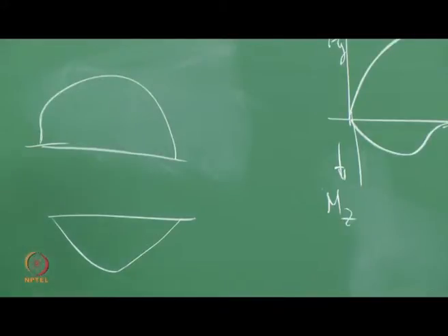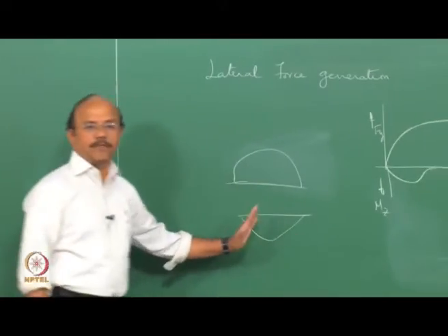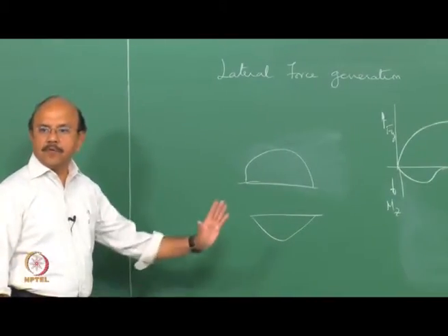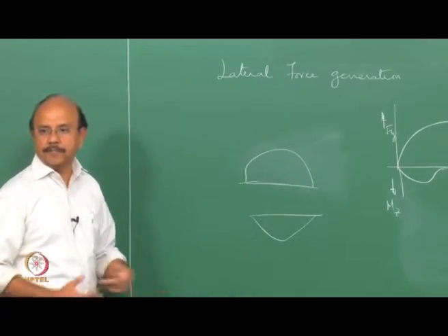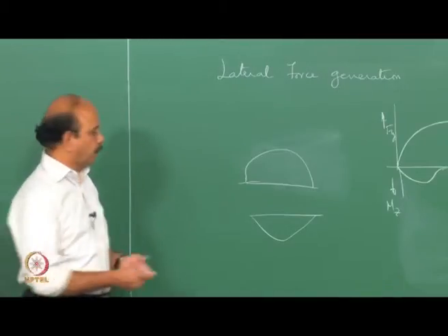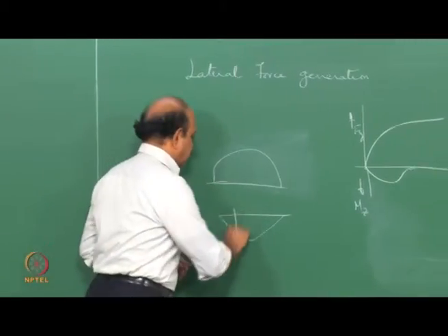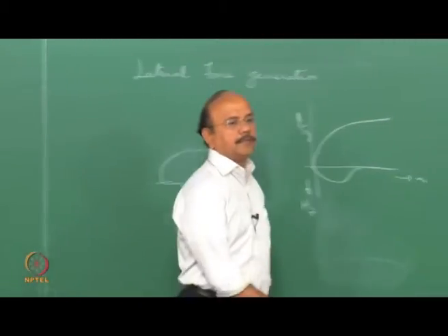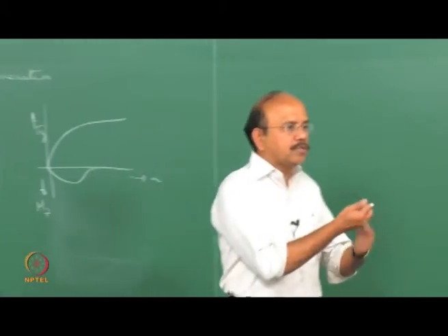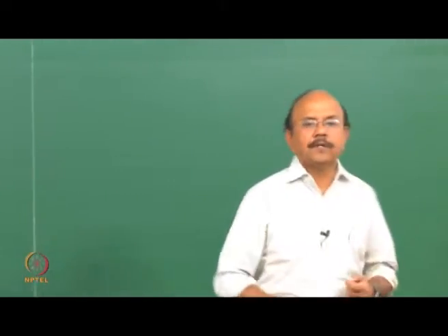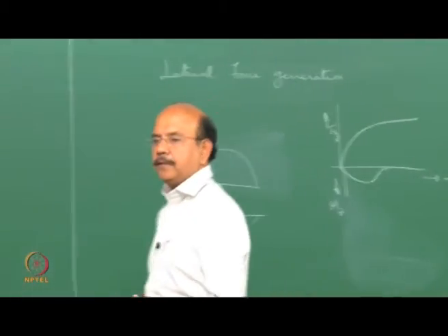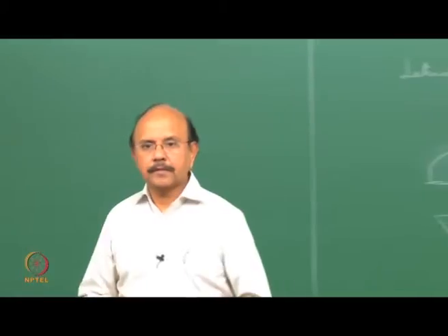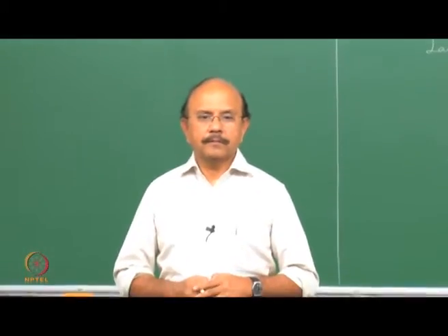Assuming that there's no slip, because it is now shifted to the left, there's an unsymmetric distribution. Obviously the resultant force, because of all those shears or pulls of those bristles, will not be symmetric, but unsymmetric, right?